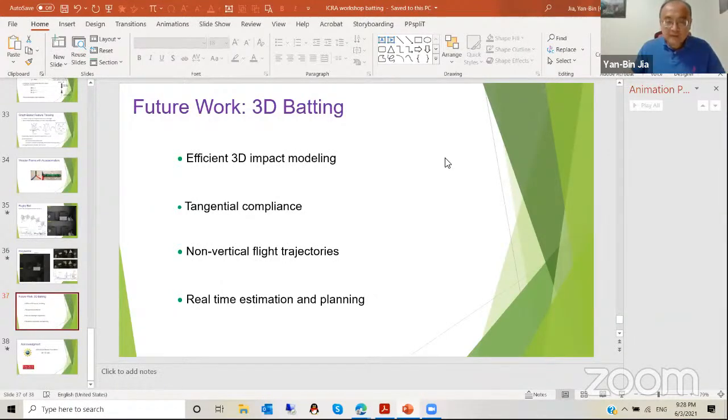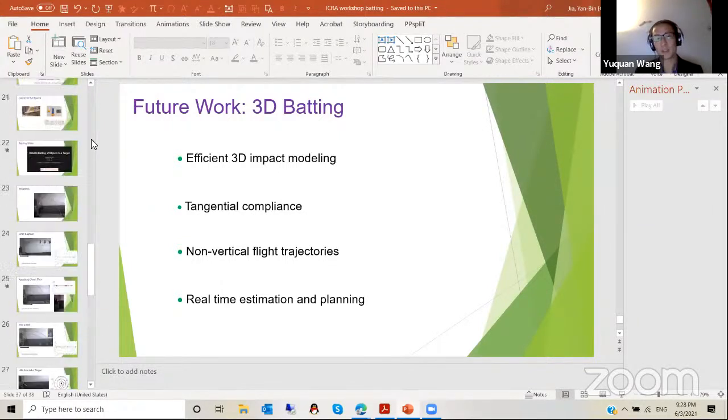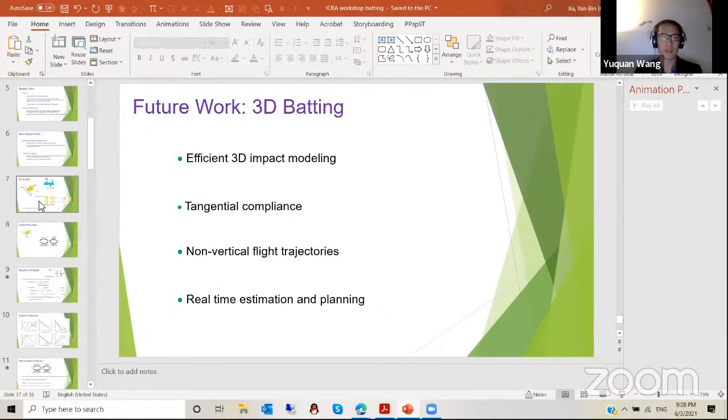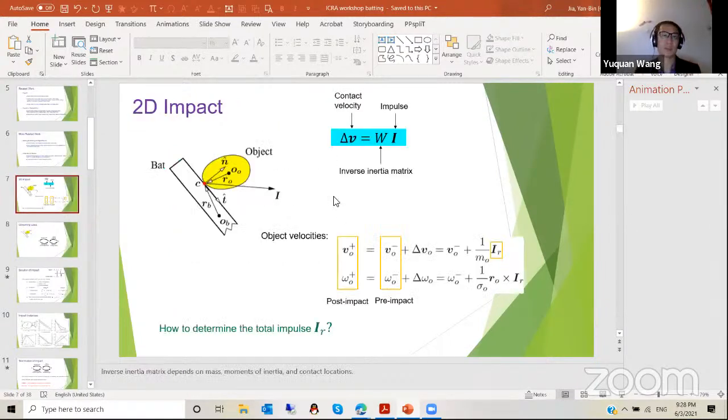Sure. So basically, in the paper, I think we covered the case when the inertia between the robot and object is drastically different, whereas in practice this assumption might not always be true. For instance, in these box grabbing examples or more common impact tasks, the object inertia is not negligible compared to the robot's. So in that case, what kind of robot inertia should we use? How do we compute it?